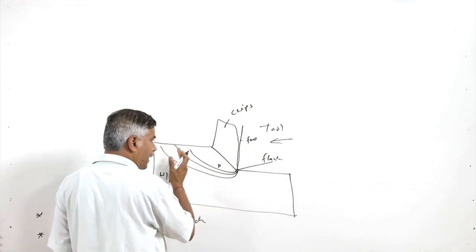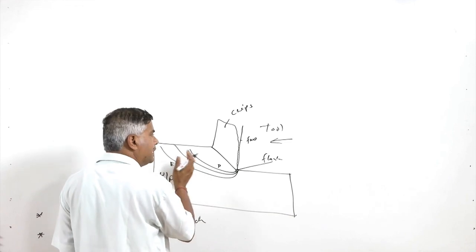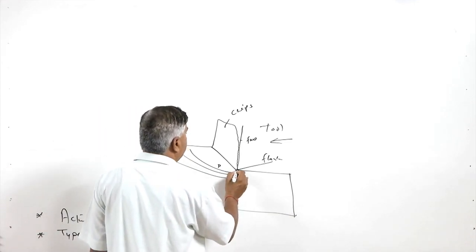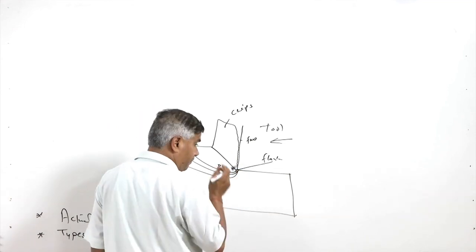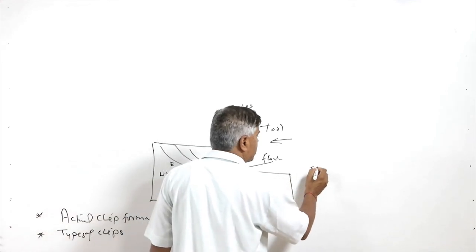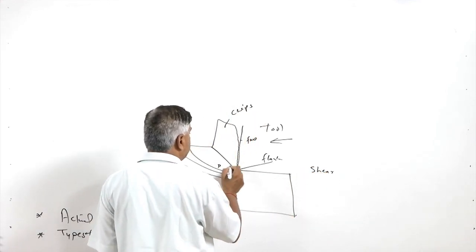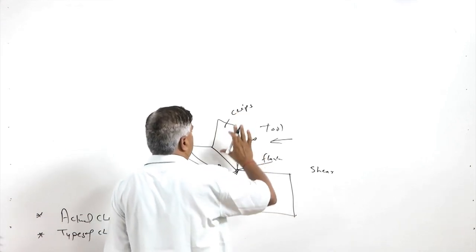but as soon as the tool approaches the regions away from the cutting edge, they will also be under plastic deformation. As soon as the stresses in the material exceed the shear strength of the material along a particular plane, which is called the shear plane, the material gets sheared off and the chips start forming.